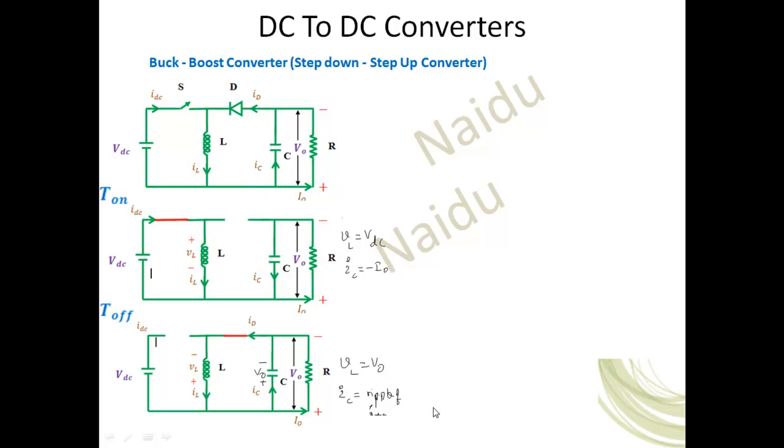The only difference is that VL is V0 during the off duration. In the earlier case, VL during this period was V0 minus VDC, but now it is just V0. That's why we can take the same waveforms.